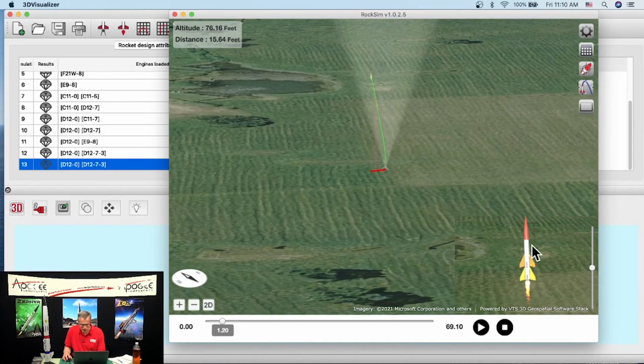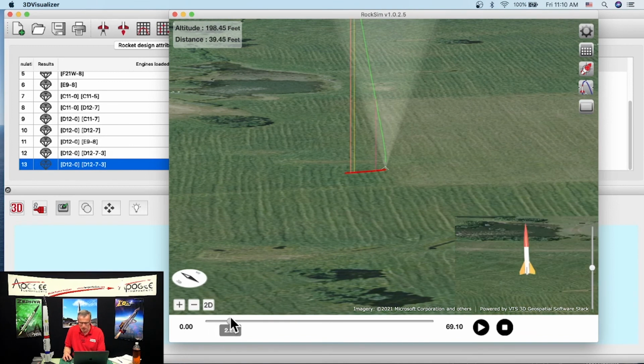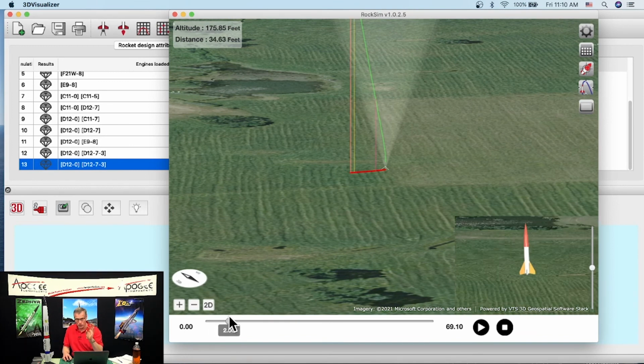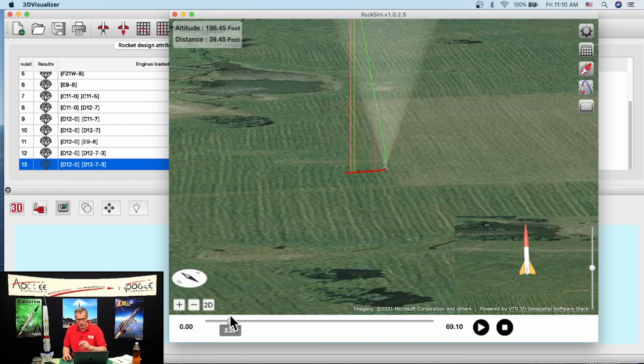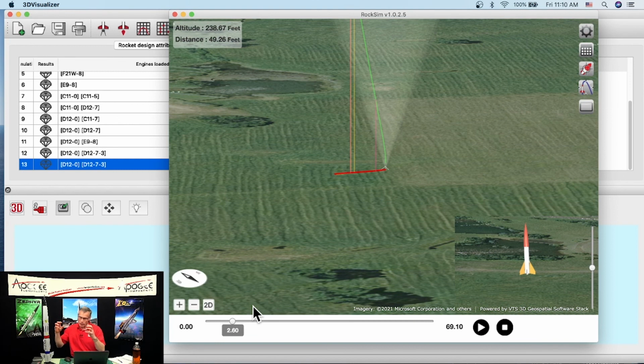But you watch this view down here, you can see that the rocket is actually spinning a little bit, but its spin rate is slowing down just because of drag. If you cause it to spin and you wanted to keep it spinning, what you would do is increase the angular, not increasing the angular momentum, increasing the rotational inertia. And to do that, you would probably put weights on the tips of the fins, so you get more rotational inertia here, and that would cause it to keep spinning. So you can also add more delay between the stages.